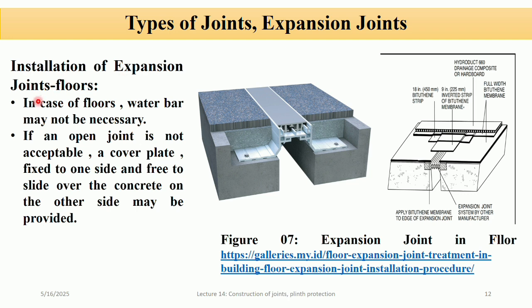Installation of expansion joints in floors. In the case of floors, a water bar may not be necessary. If an open joint is not acceptable, a cover plate, as you can see in the figure, fixed to one side and free to slide over the concrete on the other side may be provided.